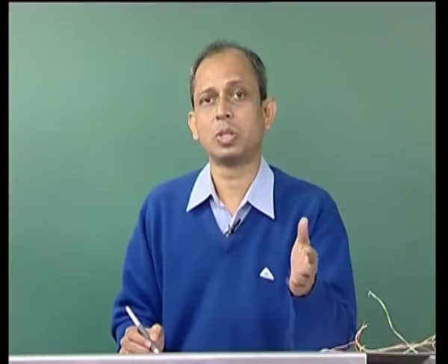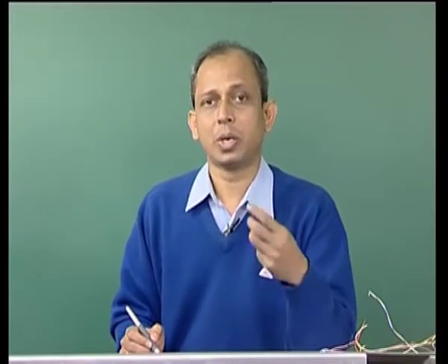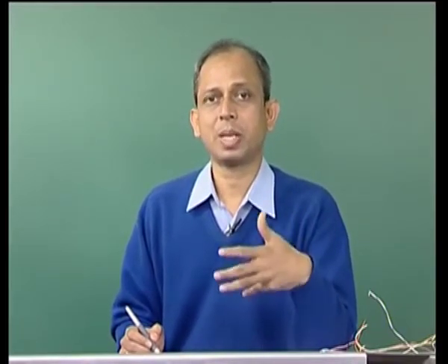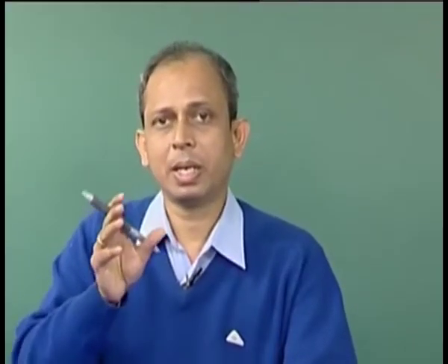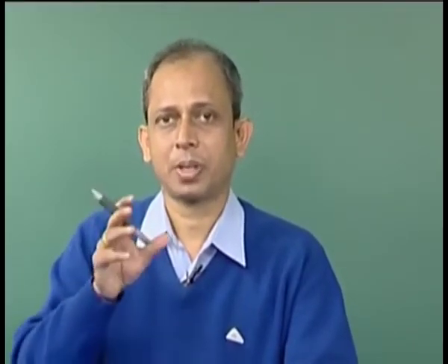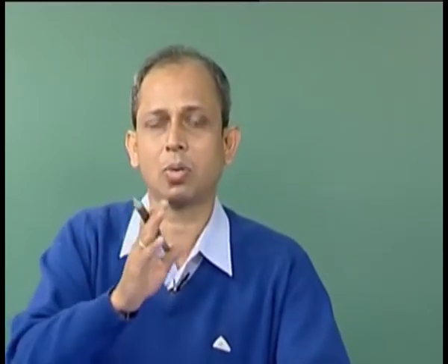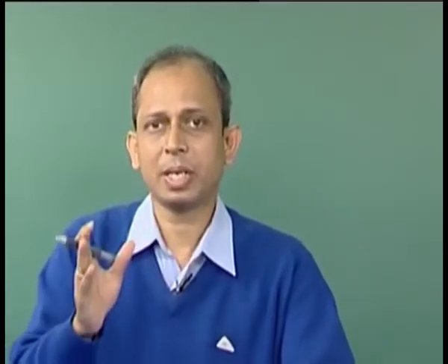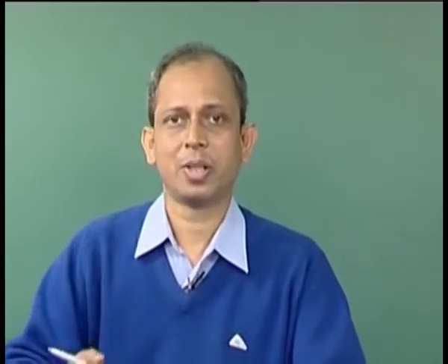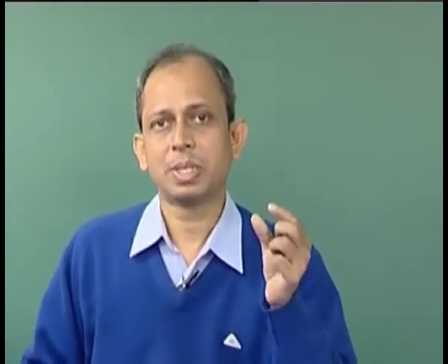So, we have already seen full step. Is there any scope of reducing the step size? Because if the step size is more, the machine will be switching in jerks. There will be a lot of jerk while changing from one to the other. The MMF is shifting in step, which may not be desirable, and this can be reduced if the step size can be reduced. So, here we have facility for micro stepping, in which we switch on phase A, then phase A and B, then phase B, then phase B and C and so on.